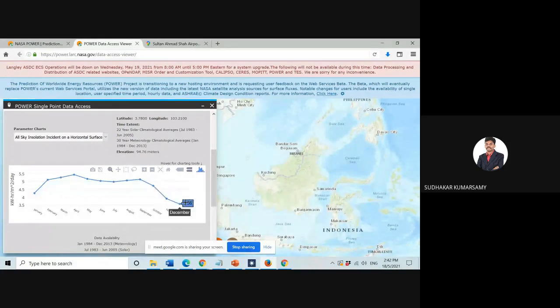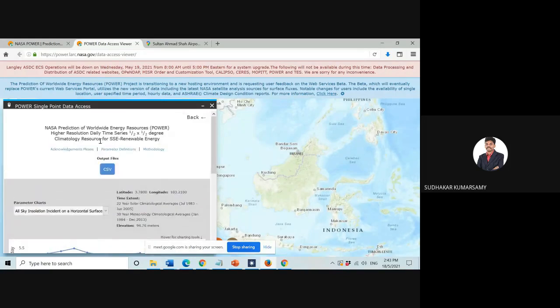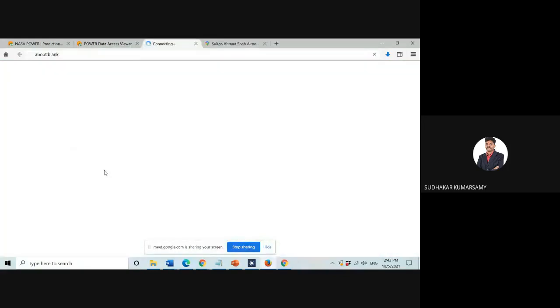You can find out the average also. Over the 12 months, you can average and get the average solar radiation for this location. Because when you go for system sizing, peak sunshine hours and the daily solar radiation value are needed, when we discussed the solar PV sizing calculation for our subject. At that time, we should know what the sunshine availability is for a given location. When you average it, you will get this value. So this data can be used, and then you want to download it. I will download the CSV file.